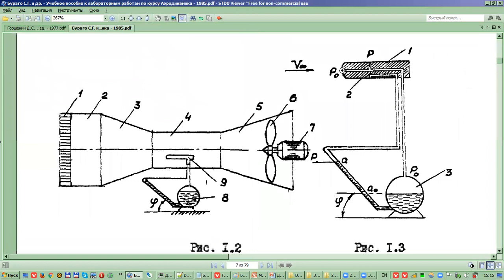You have in the Pitot tube 2 different holes. This one is P0 and this one is P. These different holes are connected with different areas, and you have different pressure in these areas. When you have different pressure, the water level increases from high pressure to low pressure.